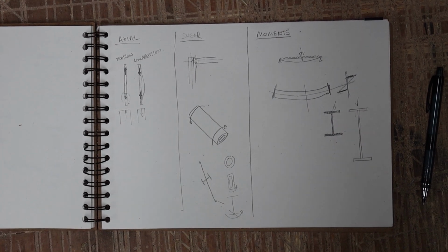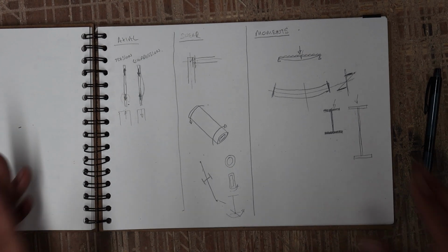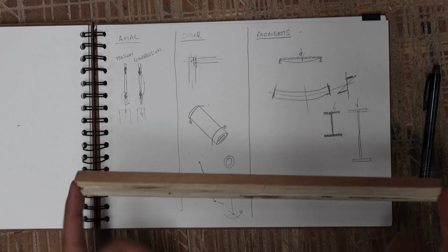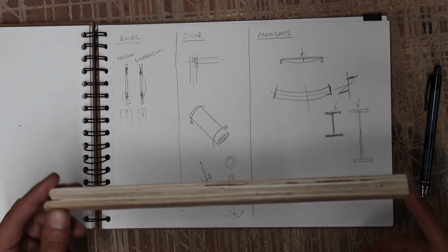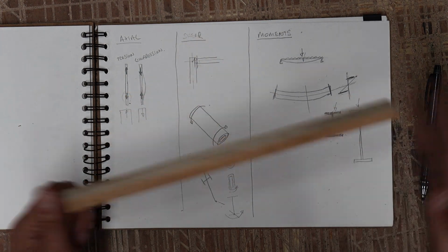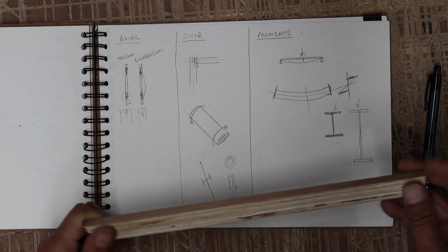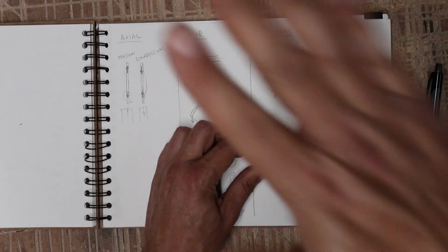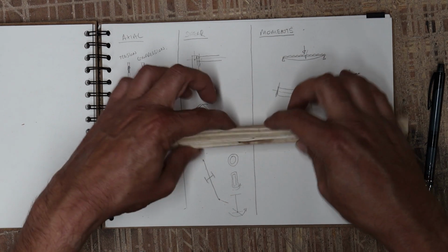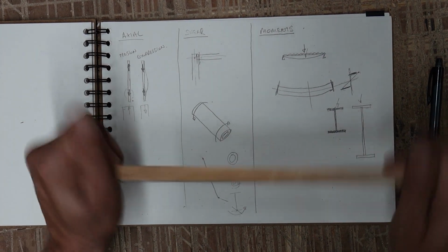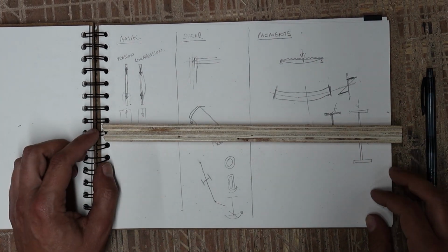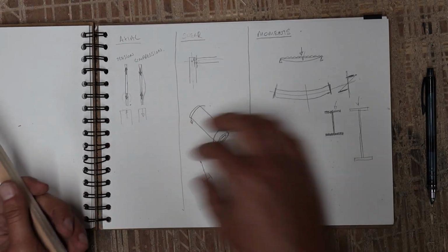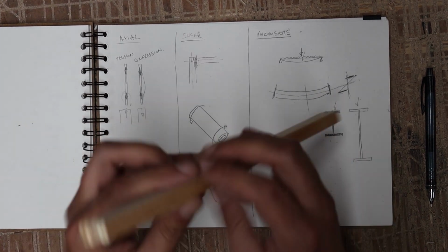So those are the things I wanted to discuss for structural basics, and this is mostly to do with individual members. Once we've done the analysis and we come up with some forces, if we put a structure in a piece of software, it will throw out a whole lot of numbers as to what a column is taking, how much force it's taking. It will tell me how much moment that beam is supporting, and how much torsion. It will tell me all of that stuff, and then from there I design these individual members, and that's where these things come in. It's the individual members.